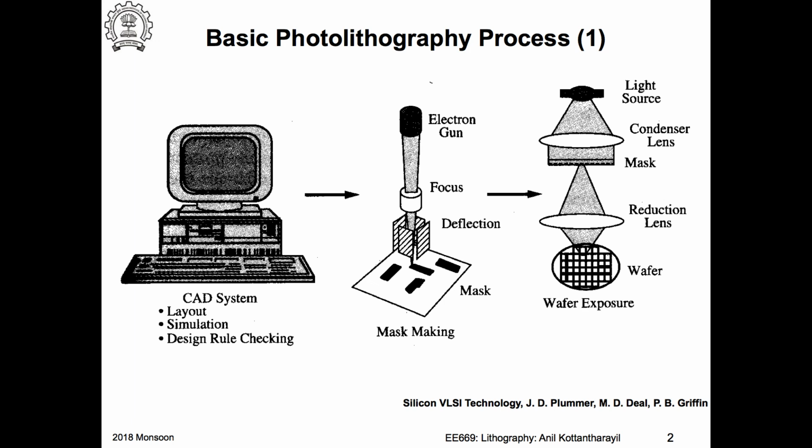photolithography system, and I have some optical arrangement. I have a light source, and then I have what is called a condenser lens. We'll see some variations of this, and I keep the mask here. This is one scheme of how you do it, and then you have another lens. You pass the light through this. The light will pass through the areas that are transparent, not through the entire thing. So it goes through, and then you are doing something here to maybe reduce the size of the image and so on. We'll discuss that later.